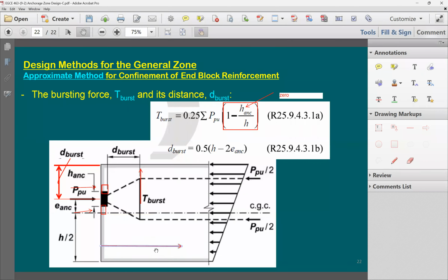In the case of pre-tension, the tension force is only going to be 2%. And here, I have the point load completely out. There's no bond between the concrete and the strands. And therefore, the amount of tension force that I need to design for jumped to 25%. This is a lot when you compare to 2%.